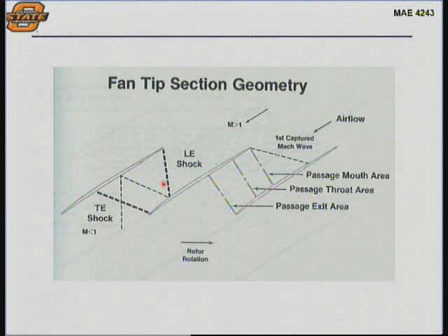Those shock waves spinning around at like 15,000 RPM, and then having blades slap into those, the ones just adjacent to the blade generating the shock, would cause a noise akin to a buzzsaw. And so it's called buzzsaw noise. If you listen to the old C-5s, which had the older engines on them before they were changed out, they had a very distinct noise at takeoff.